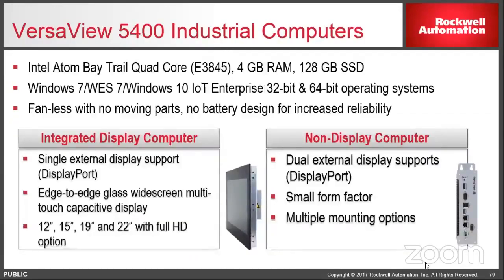The PCs use the Intel Bay Trail family of processors, which is a wildly successful family from Intel. It's the same one we're using in the MoView and in the PanelView 5310 and 5510, so it has a very long roadmap from Intel. You get a lot of work done with the quad-core CPU we're using here. Windows 7 Pro, Windows 10. Again, all fanless, no moving parts. We even use a big supercapacitor in there instead of a battery, so nothing's going to leak and you don't have to go in there and change anything.